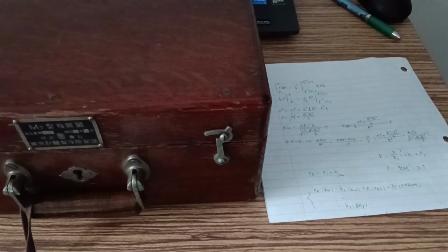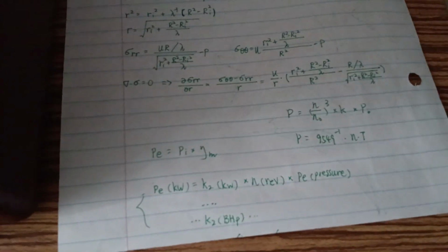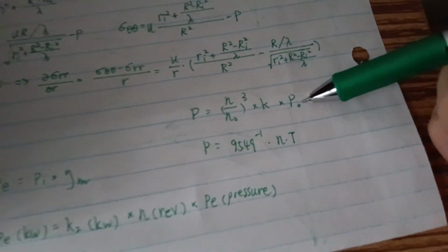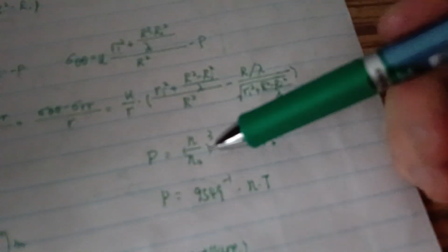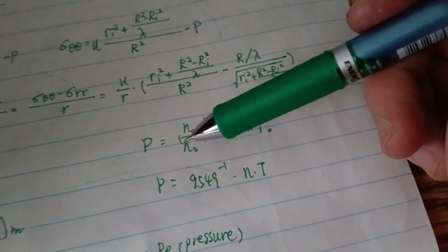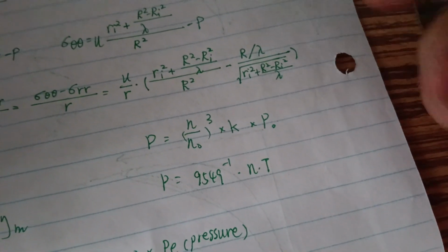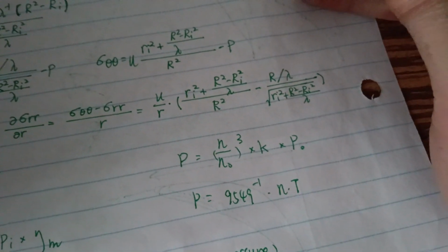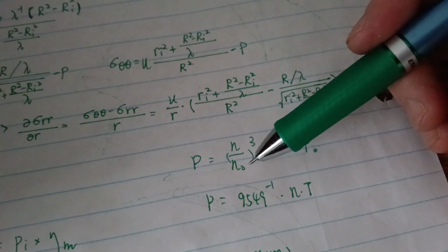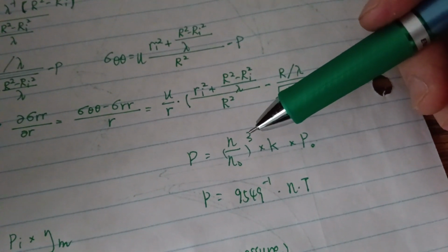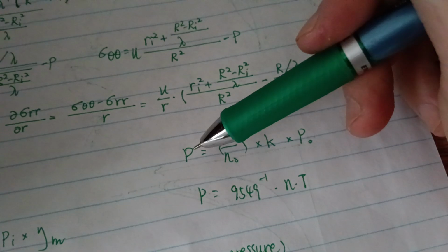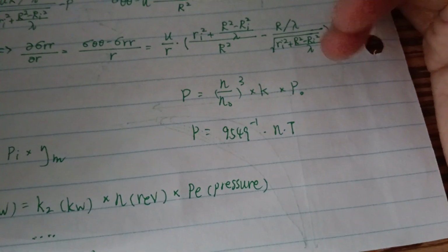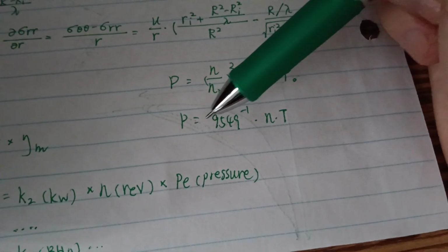So there are actually several ways to do this. The first way is like this. You use this equation here. You know this original revolution speed and the original power from the sea trial document. Also, you know this factor from the propeller manufacturer. So by the cubed law of the power the propeller is absorbing, you will know roughly how much power is delivered by the engine.